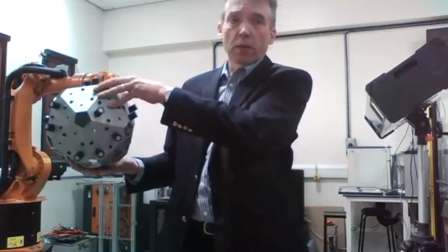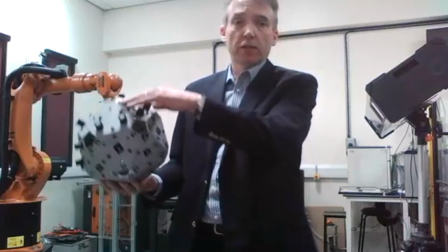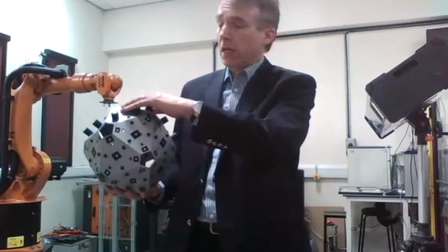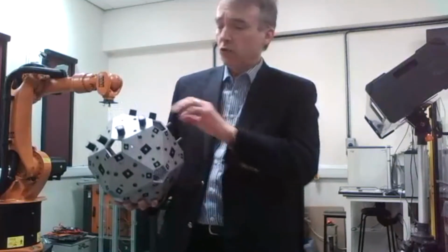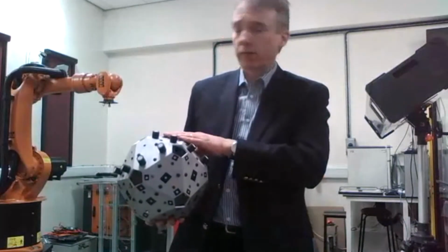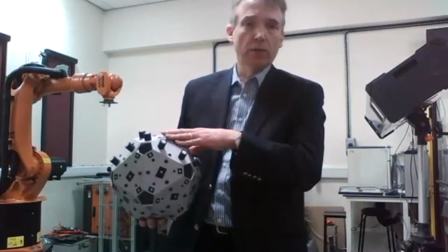And then you'd rotate the part a little bit, and then you'd do another scan, rotate a bit, do another scan, and so on. You end up getting maybe a dozen or so scans going all the way around. Now the drawback with that is that the errors accumulate, so that when you get to the 12th scan, all the way around, you find it doesn't quite match up when you try to register them.